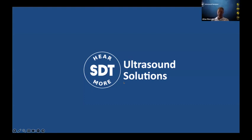Absolutely. This is outside of the scope of this presentation because I really just focus on electrical. But if you remember when I was going through the 8 application pillars, one of the ones I touched on was lubrication. And honestly, I'm in Seattle today at a reliability conference, and 9 out of 10 people coming to our exhibit booth are asking us about lubrication of rolling element bearings. So what I would say is, if you're adding grease to a bearing and the temperature is shooting up, there's a good chance that the drive-end bearing is already in an over lubricated state.